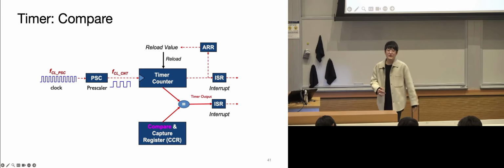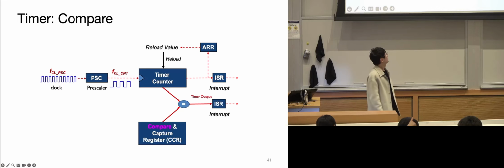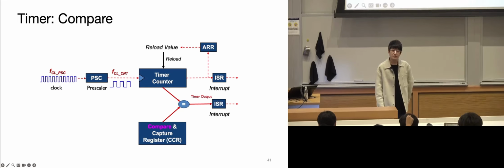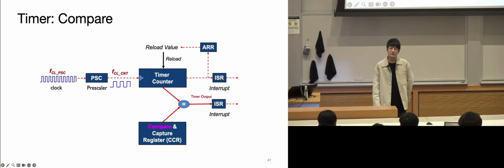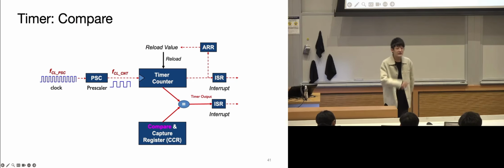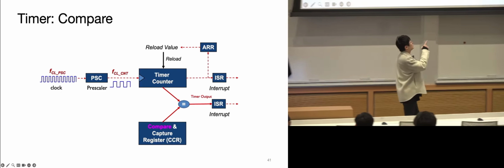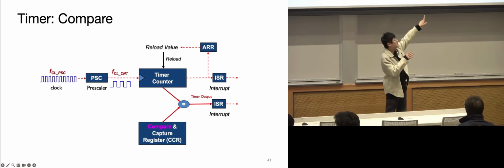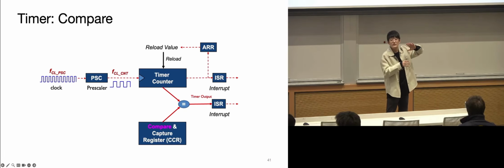Yeah. I guess what I was wondering was, the lower ISR of the two, that would not actually be used to generate the PWM signal, right? Like the PWM signal gets generated directly, and then the ISR is in case you want to do something else with it? That is actually for the PWM signal. So this will determine exactly how much percent is high or low.